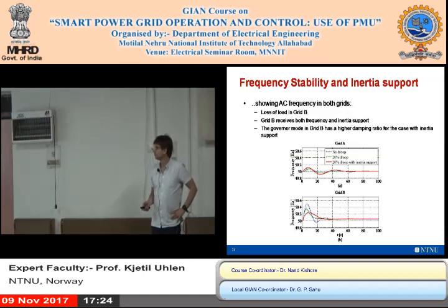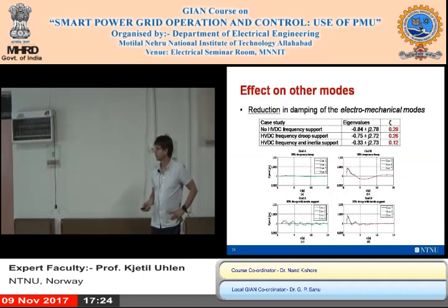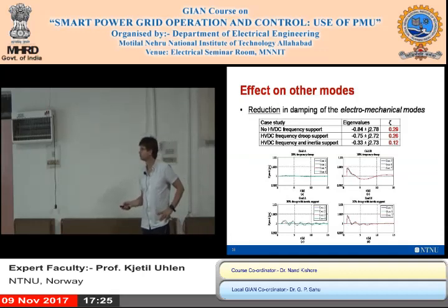Now, if you look more closely at this, here you see the time range, 20, 40, 60, 80, 100 seconds. So this is the governor mode. If you look more closely at it, you can also see that there's something happening on the electromechanical modes.